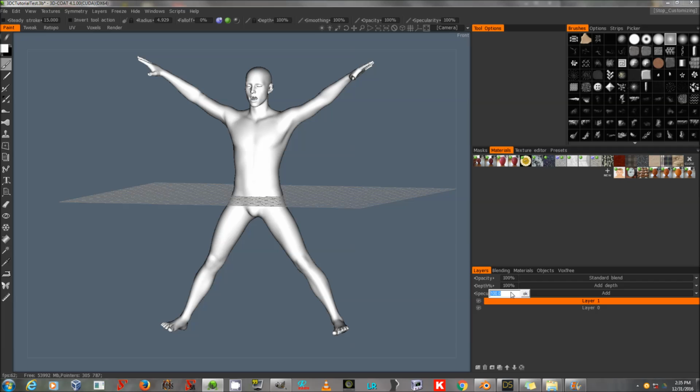And I'm going to go to specular and set it to 0% here, and do the same with depth, because we're just painting our diffuse texture here. My experience is that you can try to paint depth with 3D Coat, but I have not had good results with that.